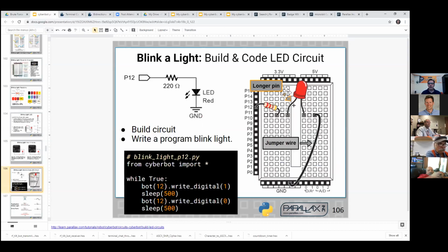And what it does is it works on this circuit right here that the tutorial has you build, a little bit more elaborate one with 2 lights, but the slide here has you build one with 1 light. And if you haven't done this, I think it's of maximum importance to try this out, make it work. And notice I called out the longer pin here. There's also a flat spot on the other side that, if you end up shaving the pins to the same length, there's a little flat spot on the actual plastic case of the LED.